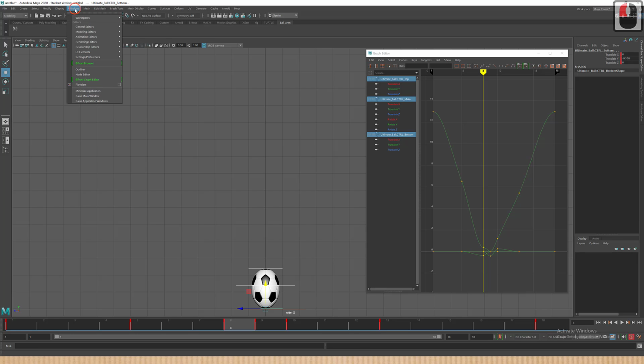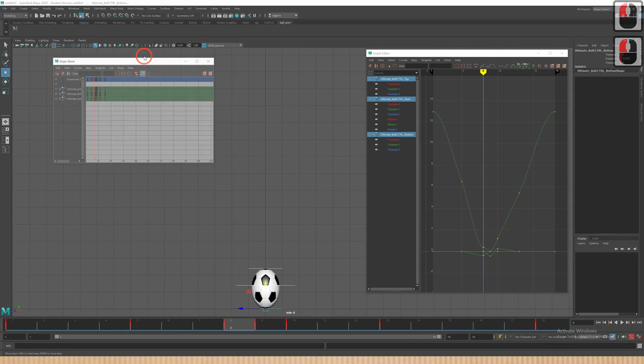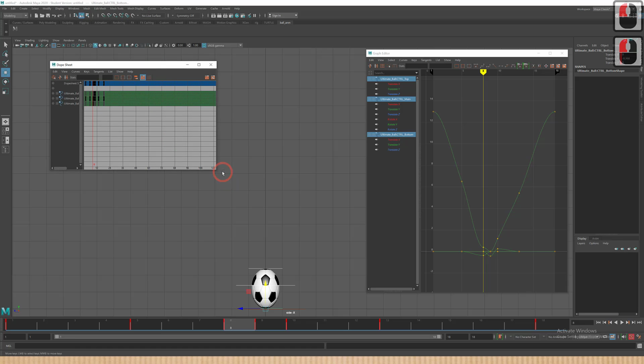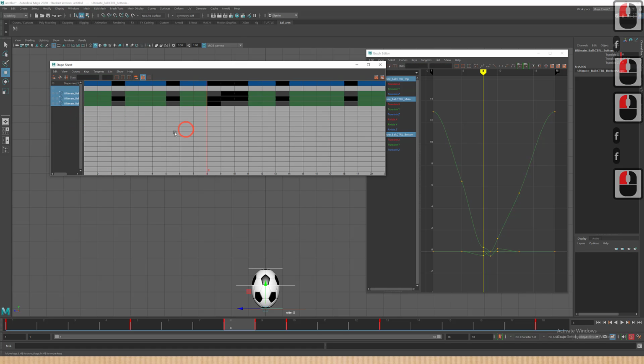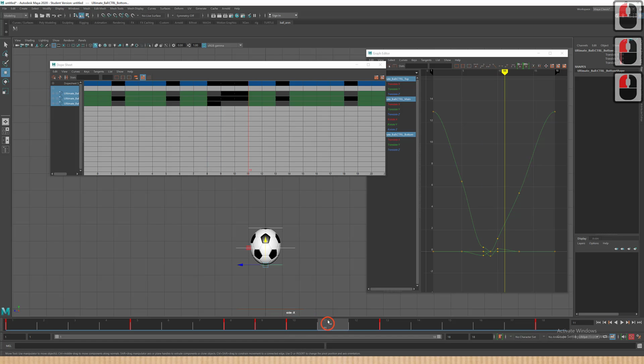You can go to your Windows animation editor, dope sheet, and just press F. It shows you the frame numbers at the bottom, and also whether all the keyframes are keyed in all frames. See to it all the controllers, for example all the 3 controllers, are keyed in all keyframes.